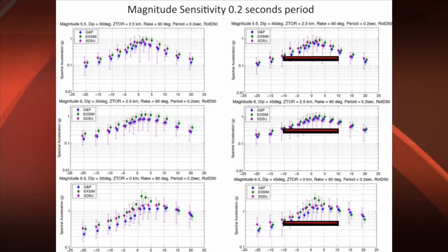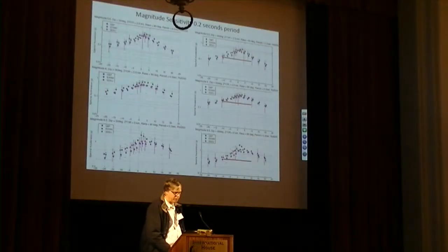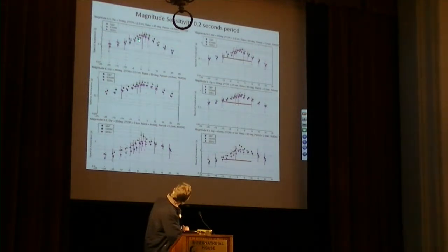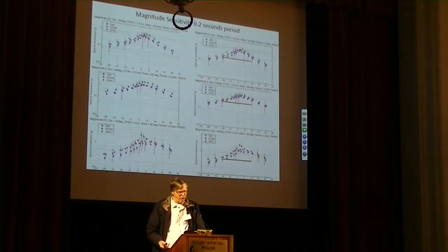2.5 kilometers. When we start to look at these, what we're seeing is the hanging wall effect. I'm going to use the pointer here. We get a skewed or pushing over of the distribution, widening out over the rupture, over the hanging wall side. You can see it's bigger here, broadening out more for larger magnitudes. You can also see what's happening on the hanging wall side by putting a straight line across, so you have a good reference point. This increase that we see comparing the footwall side to the hanging wall side is telling us about the hanging wall effect.